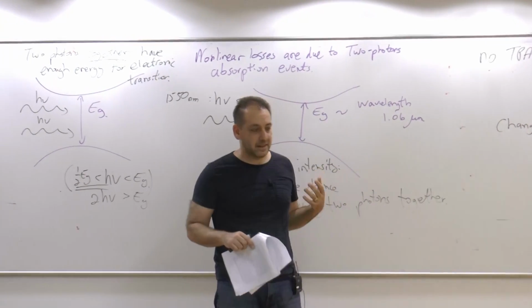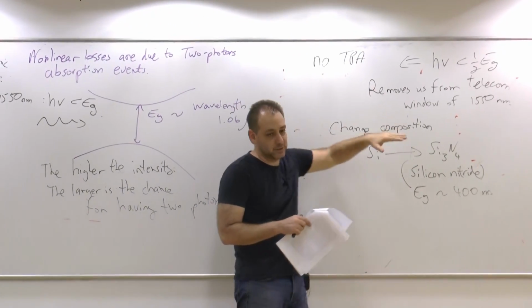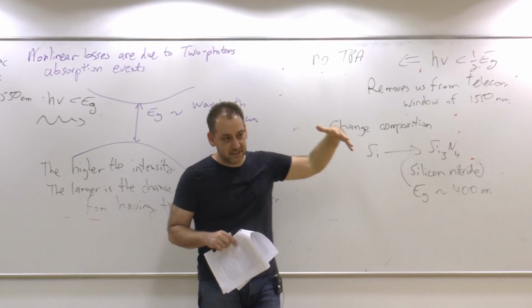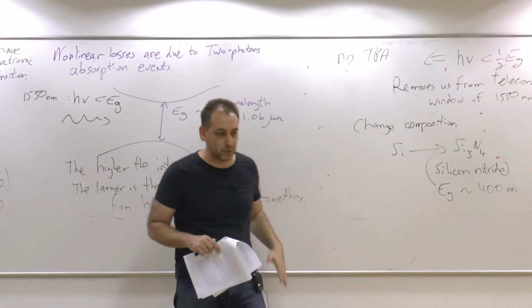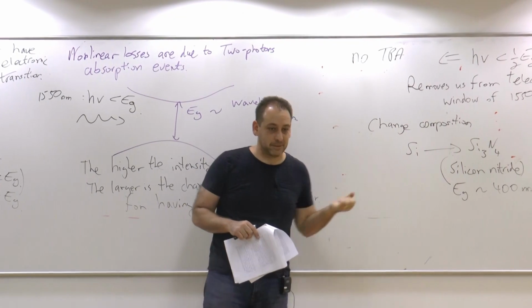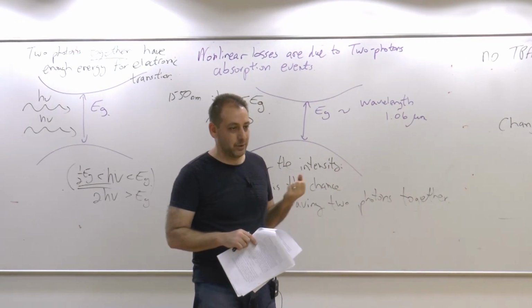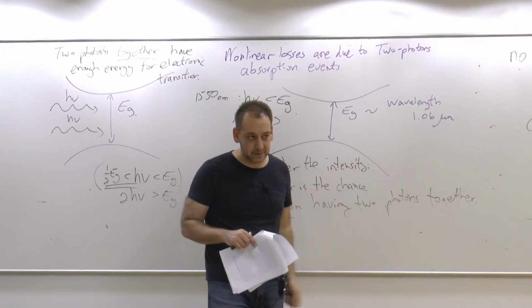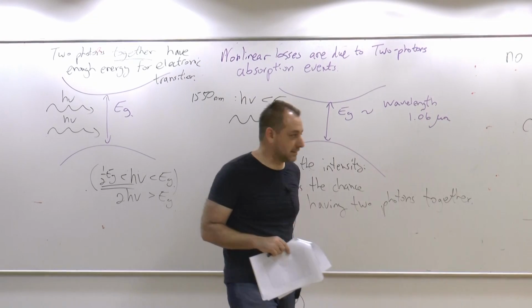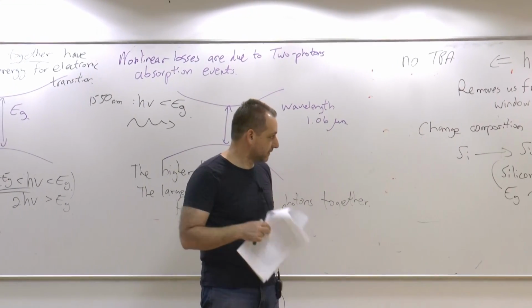But even more than that, it has very, very weak two-photon absorption because the band gap is so large. To actually see nonlinear absorption in silicon nitride, you would need 4 photons together. While this is possible, it is much less likely. So you can safely raise the power in silicon nitride waveguides much beyond what you would do in normal silicon.